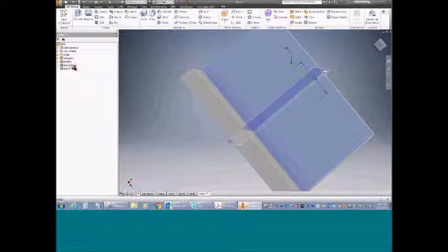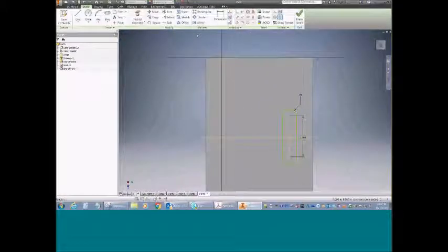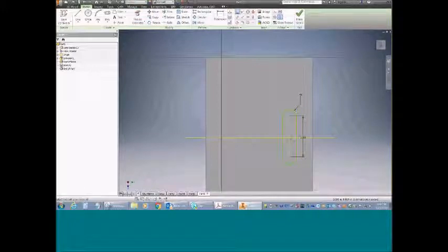And at this point, or maybe even before this point, depending on what questions have come up, I would explain the order of the tree over here: Sketch 2 in no shape, form, or fashion can see Work Plane 1 here because it's physically listed below. But there's no reason I can't just pick it up and move it, and then come back and edit my sketch. And now I'll need to project that plane onto my sketch, at least I think I will, yep. And I can just set up a coincident constraint between the midpoint there, and now it's always centered.